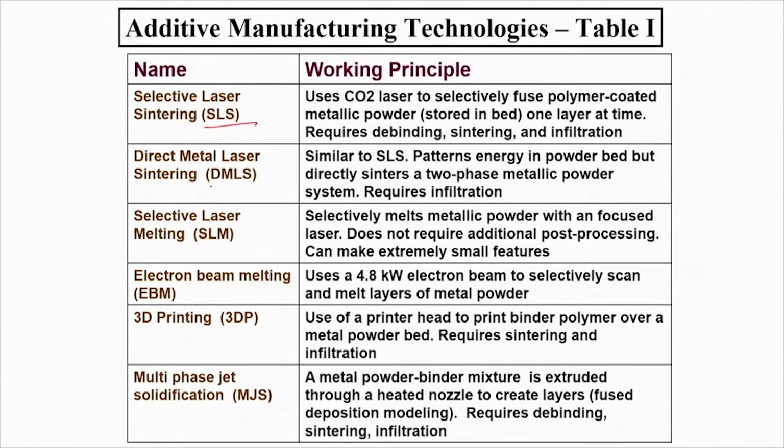When you heat, these binders melt and fuse and bond with each other. In one case you have two particles with a coating on top, and the coating fuses easily and binds. On the other hand, in direct metal laser sintering, you have two metal powders and they can fuse by a typical welding process.